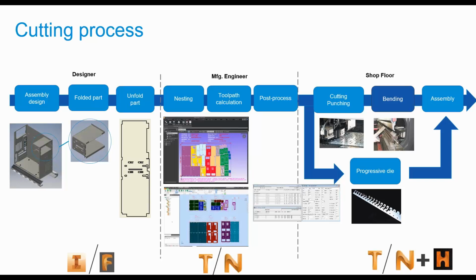The ability to group the thickness of sheets and spit out multiple sheets if need be is one of the added features of the nesting utility tool. You can leverage the DXFs generated from your nesting tool, and then bring them into HSM and generate your G codes for your manufacturing.